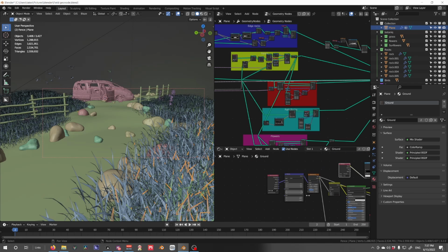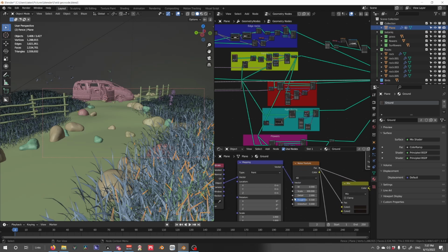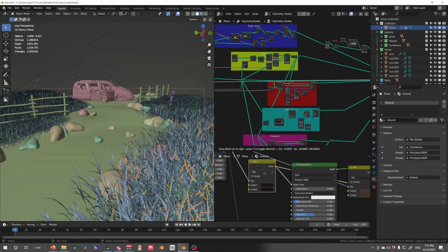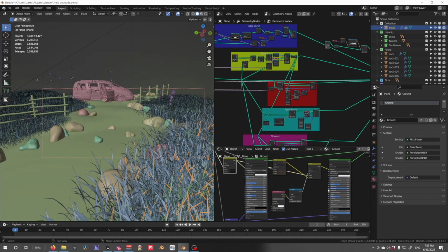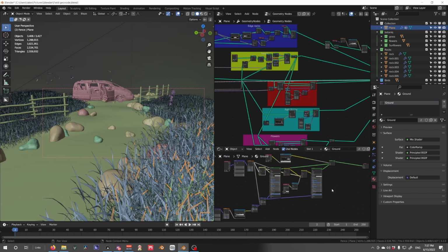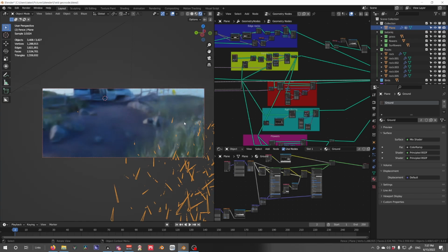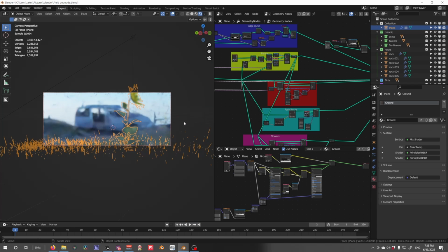So what I did was instead create a procedural setting using noise, a couple of color mixes, and ambient occlusion, just your basic procedural shader in order to get a believable dirt path. The dirt path in the end doesn't get seen that much since this is being seen in the grass a little bit, but it works for my purposes and doesn't look too bad.